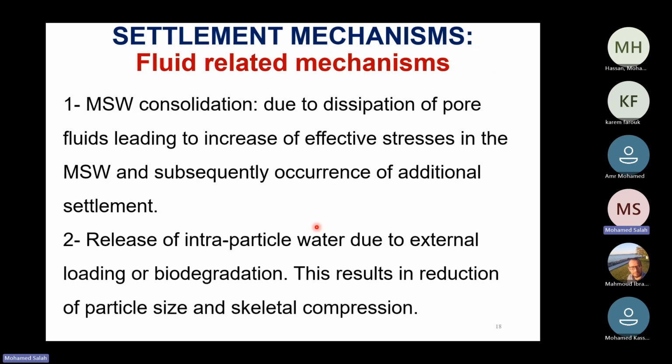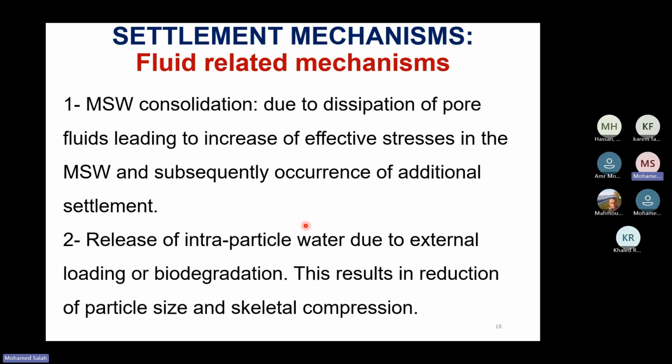The third mechanism is the fluid-related mechanism. It's something like consolidation for municipal solid waste, due to the dissipation of pore fluids leading to an increase of the effective stresses in the municipal solid waste, and subsequent additional settlements occur. The fluid-related mechanism also involves release of intra-particle water due to external loading or biodegradation, and this ends up in reduction of particle size and skeletal compression.